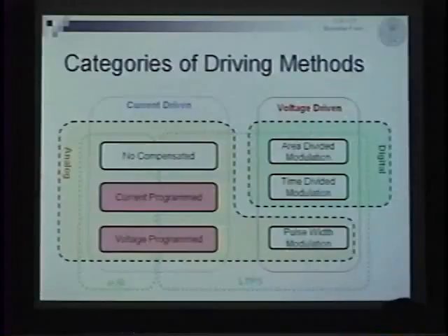In this method, the TFT is used only as a switch, so the fluctuation of the mobility and threshold voltage doesn't matter. So we can get very uniform images on the display, and it can be controlled in half-tone precisely.